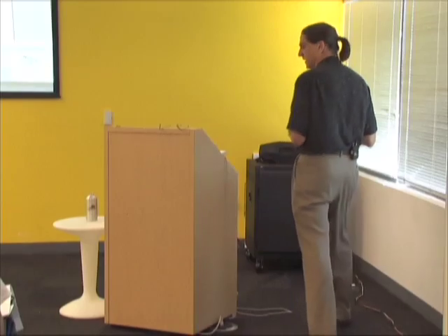You need to really isolate geometry in a large model for a lot of reasons. When you work with stuff, if you click on a surface and it's all interconnected, it's going to drive you crazy. And you just can't organize the model in the end. That's what I'm going to end up talking about in a few minutes. If you don't isolate it, you isolate it using groups and components.